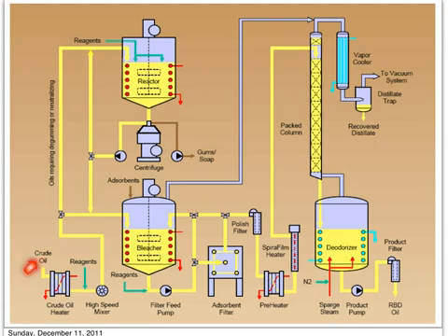This is crude oil. It will pass through a heater or a heat exchanger. The oil will be heated to increase the temperature and reduce the viscosity so that it can flow easily through the processing line. At this point, some reagent will be added for the degumming process. This can be in the form of phosphoric acid or citric acid, if we use acid degumming, or we can also use hot water if the oil contains hydratable